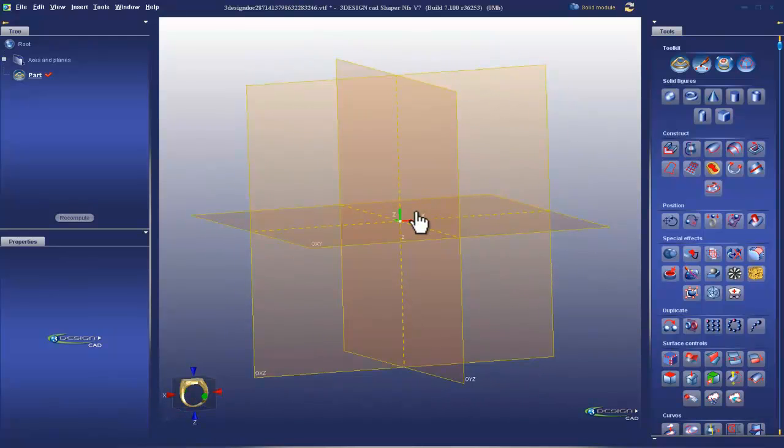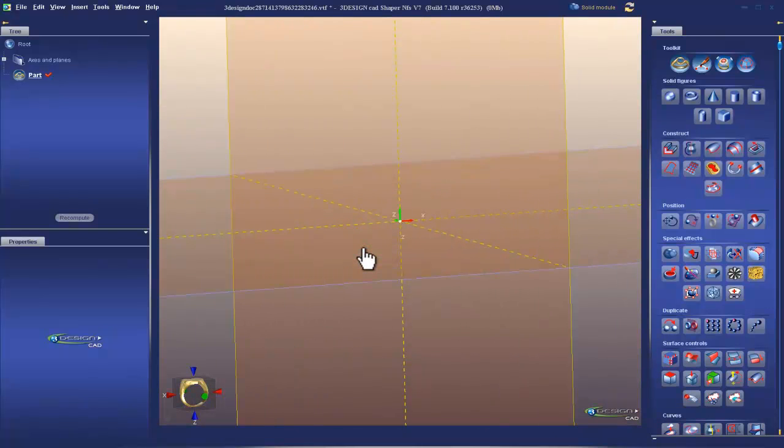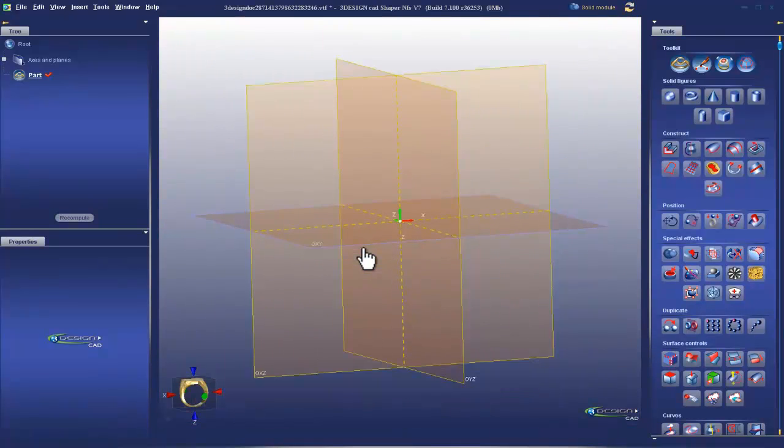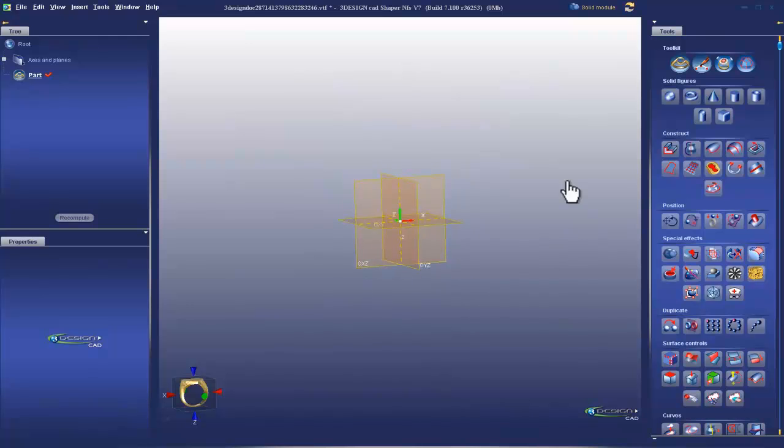The third mouse button is the track wheel. If you pull the track wheel towards you, the workspace zooms in. If you push the track wheel away from you, the workspace zooms out. So the left mouse button selects, holding Control and the left mouse button multi-selects, letting go of Control and reselecting unselects. The track wheel zooms, and the right mouse button allows you to twist the workspace.